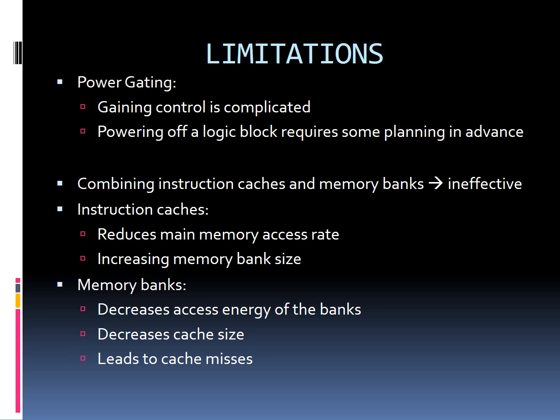These are some of the limitations that I observed. Although power gating mechanism can greatly reduce the power wastage during idle mode, its implementation exhibits some complications due to which it has not become a common ASIC technique yet. Powering off the logic block requires some planning in advance, as the logic might be needed even before some power restoration gets done. Unlike clock gating, gaining control over power gating cannot happen with ease.